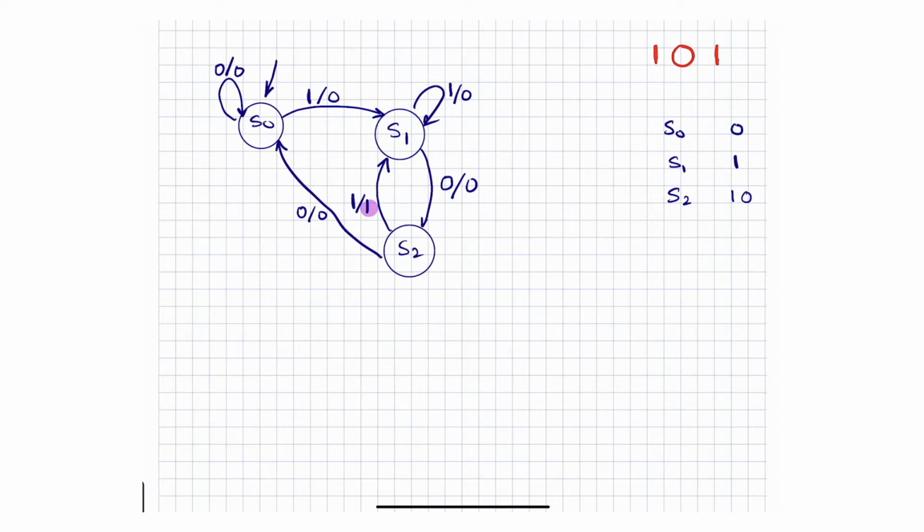So we figured out that we need a sequence detector, and we figured out what the state diagram should be. I can technically go and input this in my CAD software using Verilog or any other HDL for that matter, and the CAD software will figure out the rest of the steps for me and figure out the implementation. So this is the important step in here, which is usually done by a human. You can't just offload this to a computer. But the next steps are so mechanical that you can.